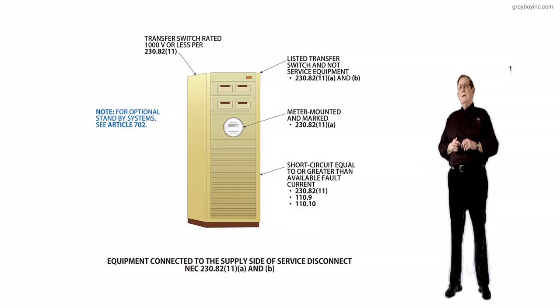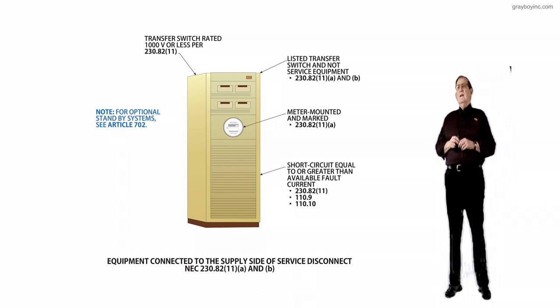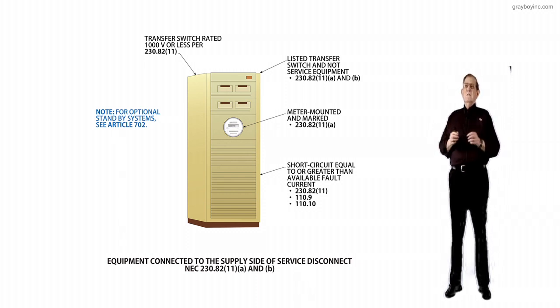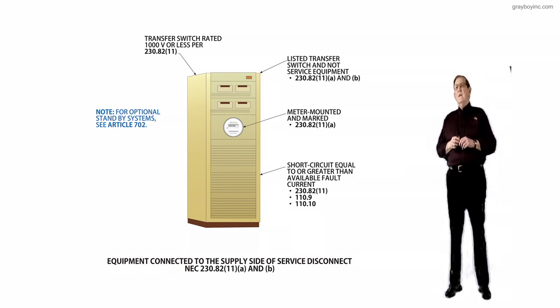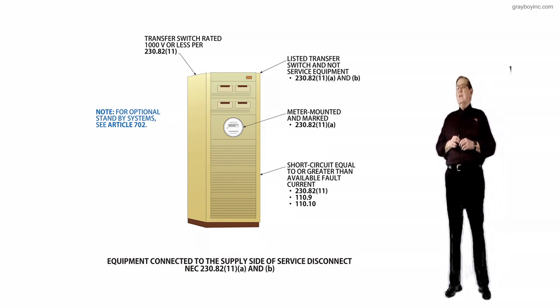Now, notice one other thing in this short circuit current equal to or greater than. What the problem was here, in the old days, the city in some places and counties and states would require that if you had 10,000 amps of short circuit current, that's just an example, hitting this, that you would hit it with no more than 80%.